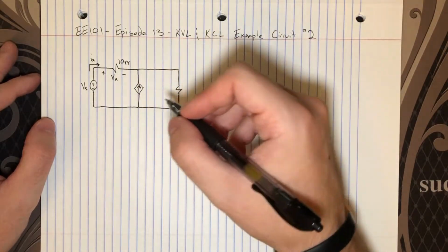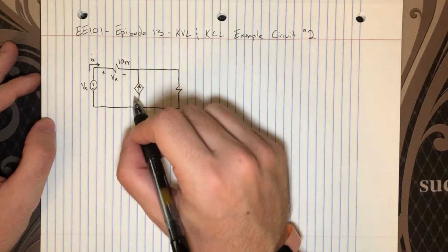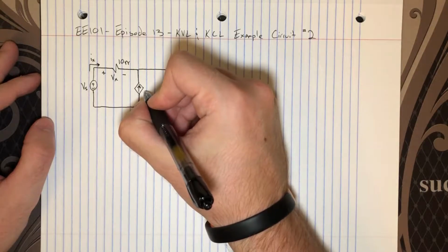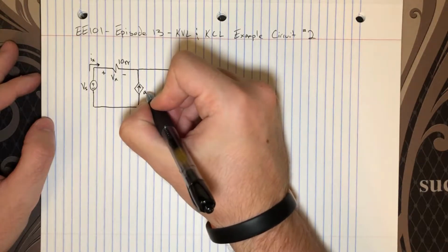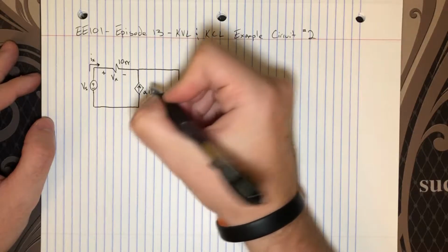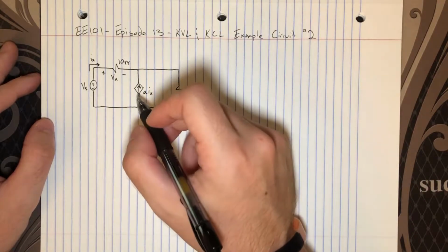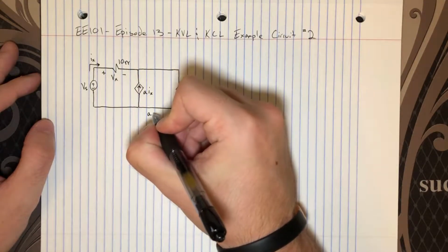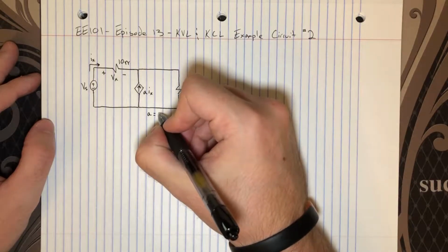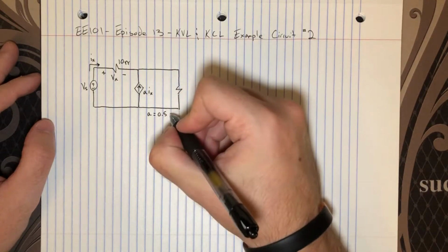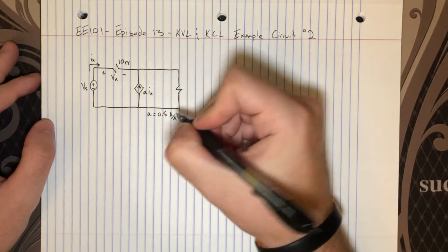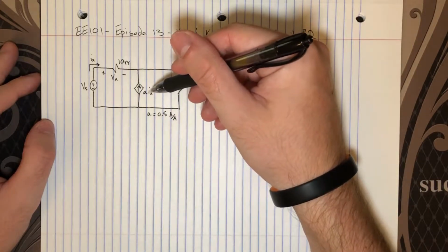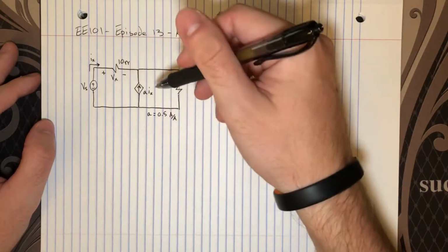This dependent current source is going to have a certain relationship with the current Ix. So we're going to say that the current here is A, some constant, times Ix, where Ix is another current in this circuit, this one that I labeled here. And A is a constant that I'm just going to label down here. We're just going to say that we know it in this case, and A equals 0.5, and the units here will be amps per amps, which really isn't units at all, so it's just a constant, and it's saying that this current is 1/2 of whatever Ix is.